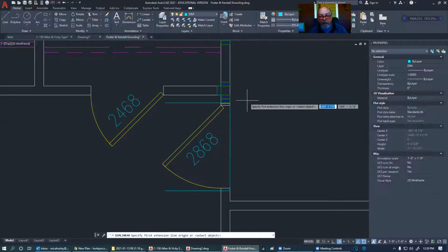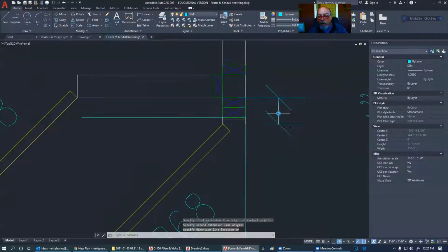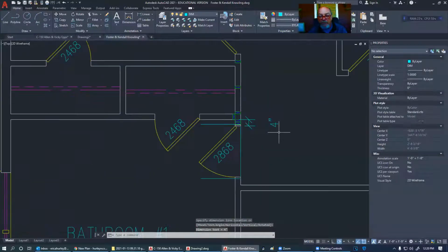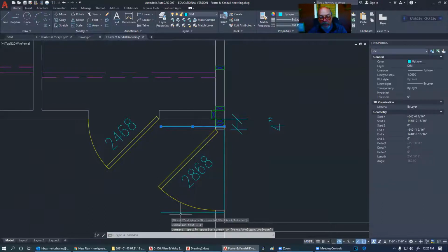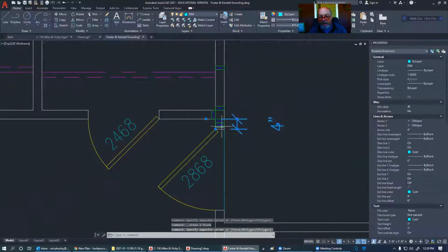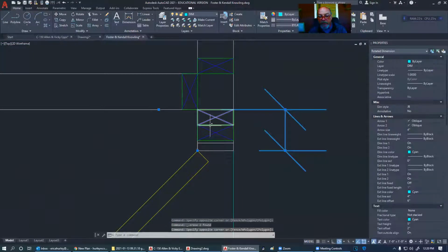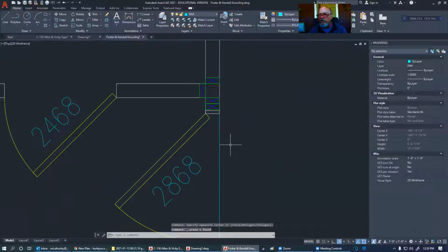So from the edge of this to your door, you're looking at a total of 4 inches, bare minimum. This door, if built properly, cannot be any closer than 4 inches to a wall, so that we get enough space in here for the components that are in this wall to be placed into it. Does everybody understand so far what I'm saying? Okay.